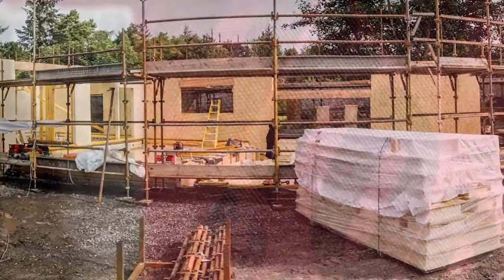Everybody wants to put lots of insulation in, and sometimes the amounts and thickness of insulation that you put into a building can be quite frightening as you lose floor space as you insulate further. One of the best ways, which we show on our website, is to improve the air tightness of the building, which doesn't have an effect at all on the footprint. You're just replacing the breather membrane with an airtight, self-adhered membrane wrapping around the building, similar to what you did on your project where you improved the air tightness.